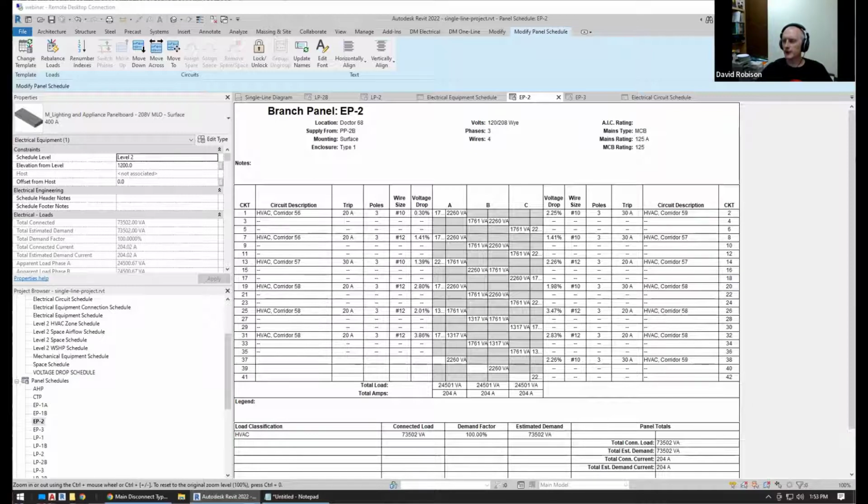So then there's the question in the chat. Would you recommend to replace all the default Revit parameters to the Design Master ones? So you'll want to replace the Revit parameters that we have replaced. So that's mostly the mains type and the breaker rating for the panel itself. And then on the circuits, all of the wire sizing stuff, you would want to use our values because the Revit wire sizes are not going to be correct. Because Revit does display a wire size, but doesn't give you any control, and so we can't modify that. So you don't want to be displaying the Revit wire sizes.